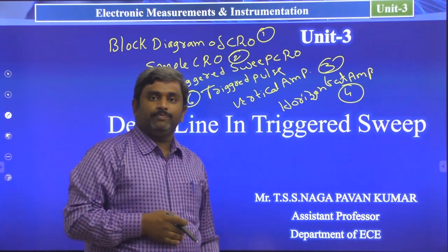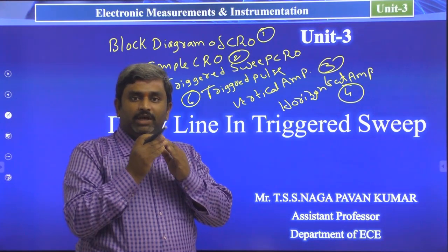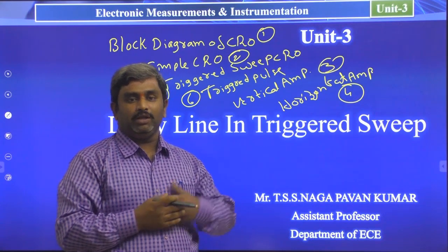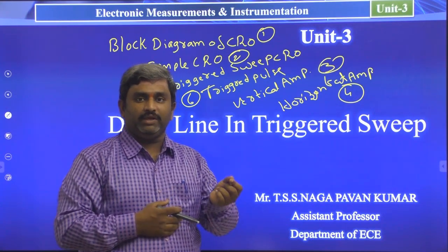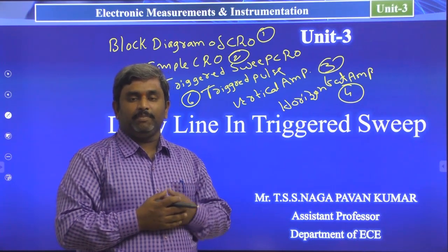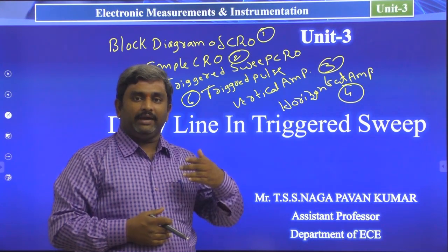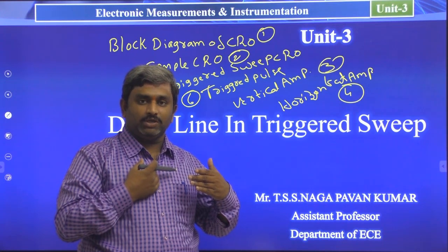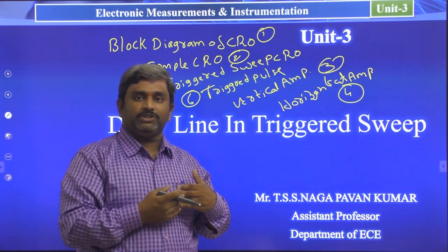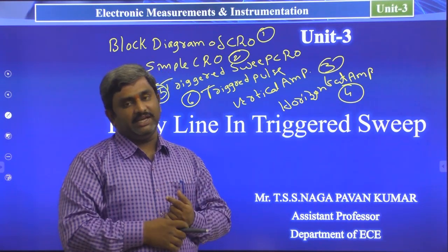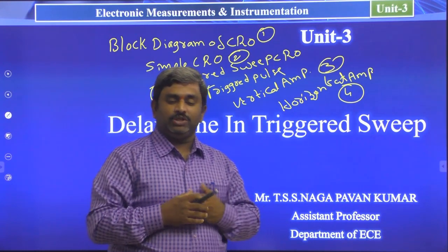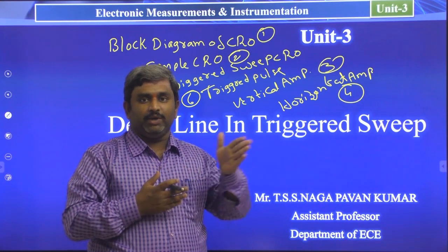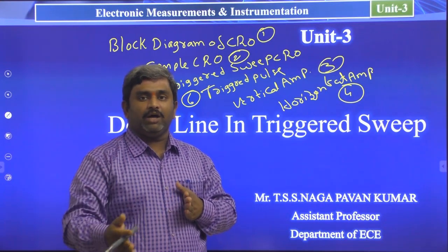Right? So here for the oscilloscope, we have 2 input channels or maybe 1 input channel. At the input channel side, we are giving some signal by using a CRO probe, and the main motto of our oscilloscope is this signal information has to display on the CRT screen. So when it is taking this signal, we have 2 paths, the vertical direction path and the horizontal direction path.